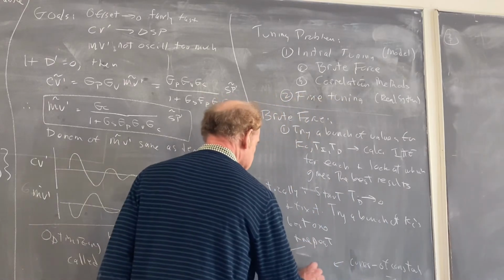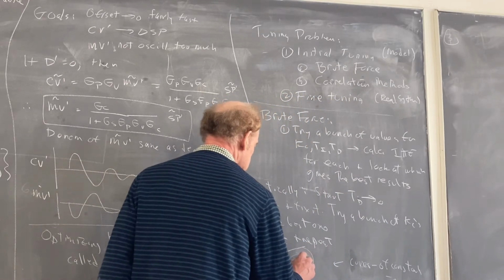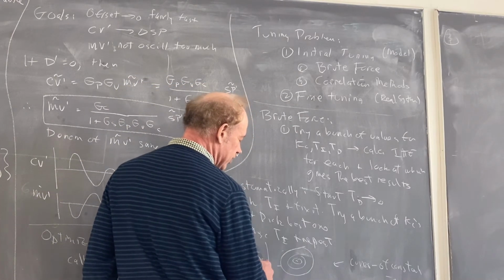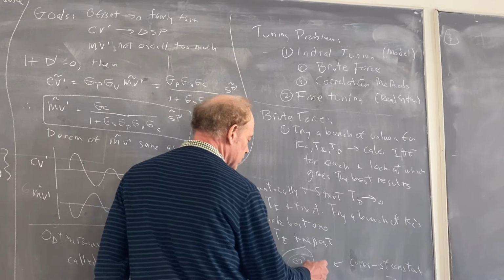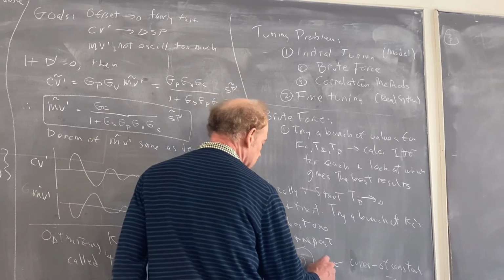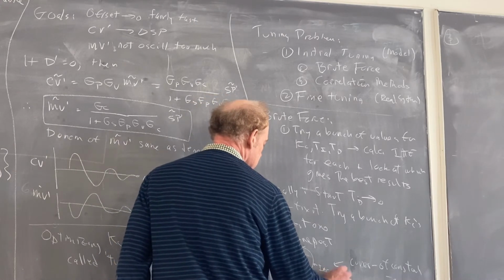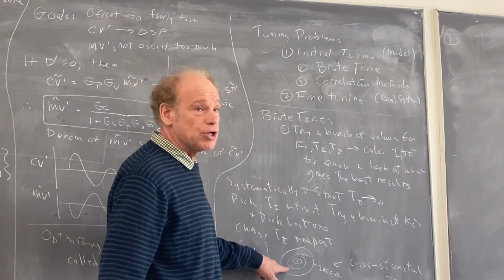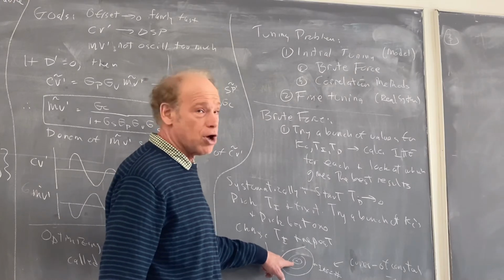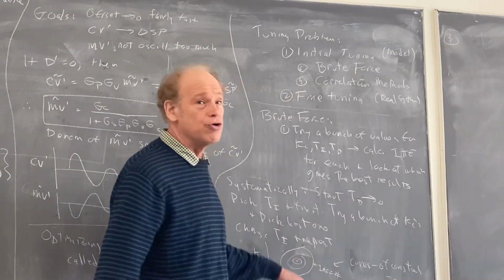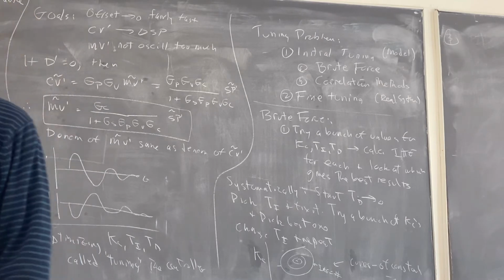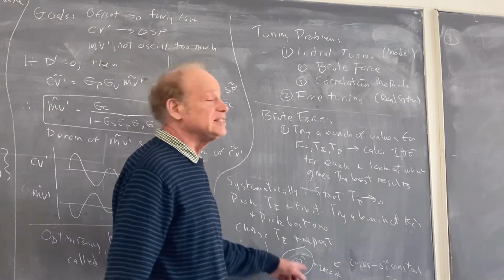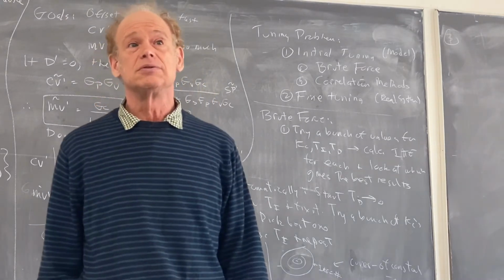You hope to get plots that look something like this, where everywhere along this curve, for all the KC, Ti values along this curve, I get a particular value of IAE equals a certain number. And the inner one is similar, but the number is a little smaller. And then you try to hone in on the point in the center where the value of IAE is the smallest, and that gives you the best value of KC, Ti by brute force.